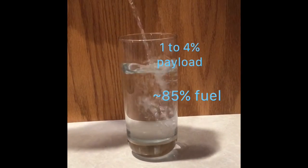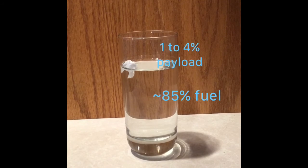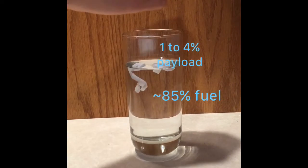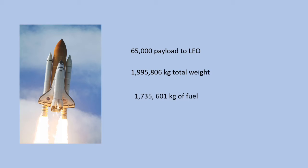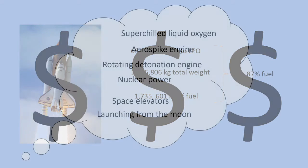Thankfully, with some smart engineering, we can get rockets to the point where they're about 85% fuel, with 1 to 4% being the payload depending on the size of the rocket. If we look at the space shuttle, it could carry 65,000 kilograms of payload into low Earth orbit, and in order to do so weighed nearly 2 million kilograms total, with approximately 87% of that being fuel. You can see how the rocket's fuel inefficiency makes the cost quickly add up.